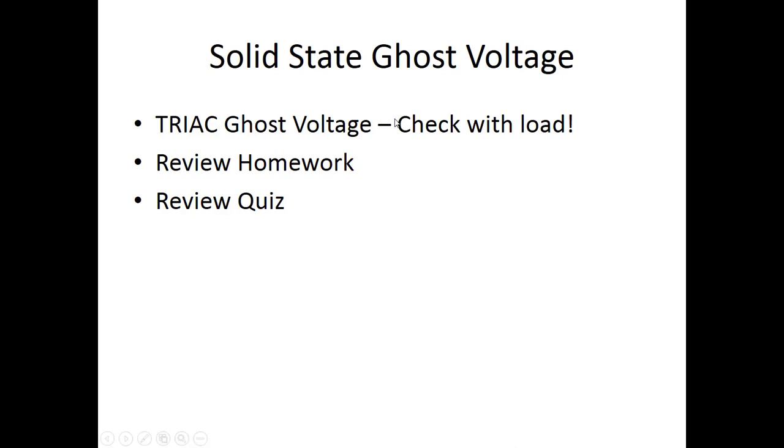The moral of the story is if you're not sure, check these with a load. You can get a small light or something like that, like what we did, and you can touch it, and if it's truly got voltage there, it will come on.